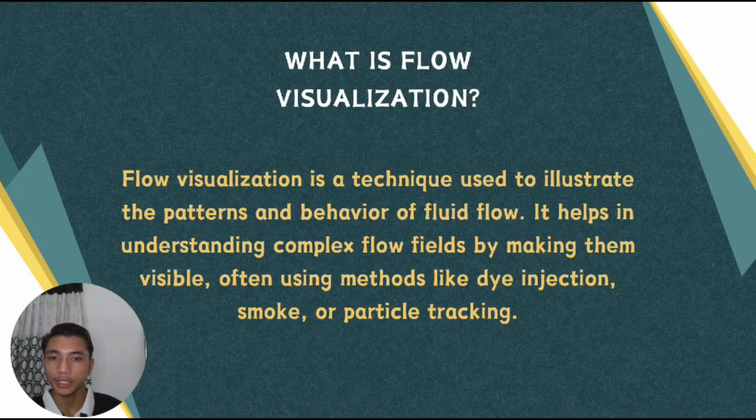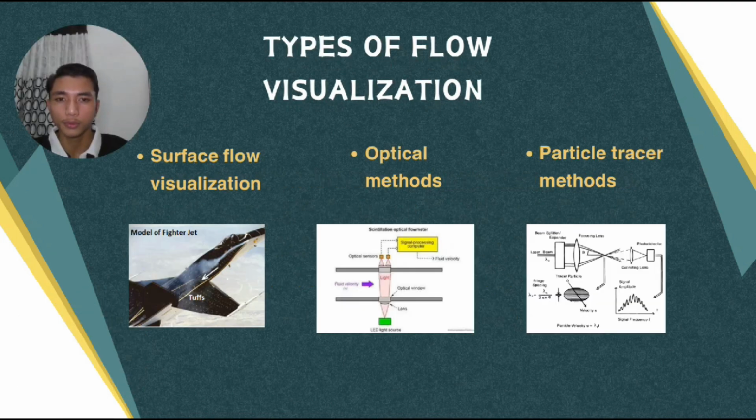Flow visualization is a technique used to illustrate the pattern and behavior of fluid flow. It helps in understanding complex flow fields by making them visible, often using methods like dye injection, smoke, or particle tracking. Next, we move to types of flow visualization. First, we have surface flow visualization. Second, optical methods. And lastly, particle tracer method.